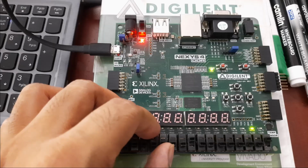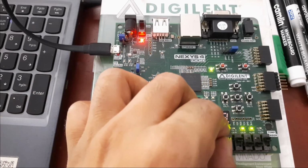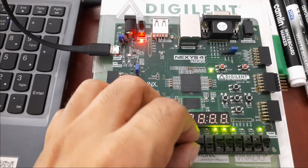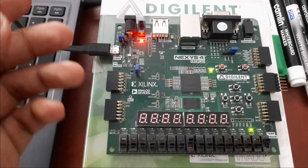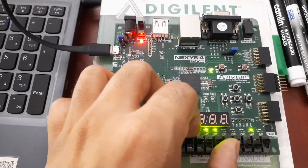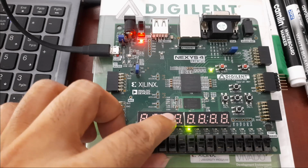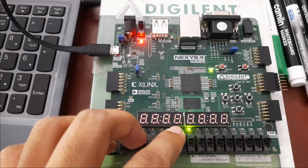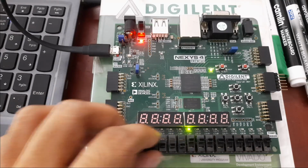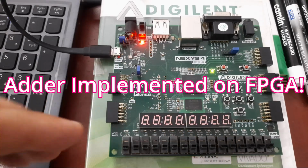Whatever you want to add in binary, you can just add it here and check it here. For the last thing, we can check the overflow, the 9th bit. If we have 255 added with 1, we will get 256 and the 9th LED is on. This is the one extra LED that we have to assign, right? So this is the FPGA implementation of the 8-bit adder, and we will do the subtractor now.